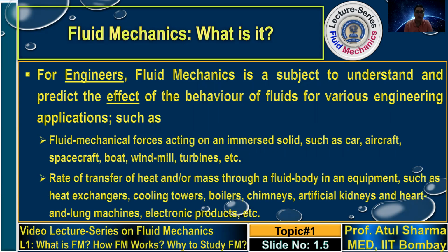The fluid flow also affects heat and mass transfer. Like if you consider a heated object and the fluid is flowing over it, then the fluid flow affects the rate of heat transfer. If the fluid is stationary, then there is only one mode of heat transfer, which is called conduction. Whereas when the flow starts, the additional mode of heat transfer is called advection. And the combination of conduction and advection is called convection. So the effect of the fluid flow is that it affects the rate of heat transfer.